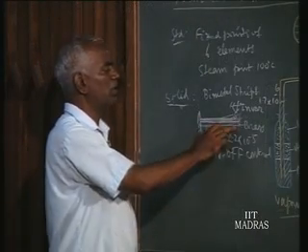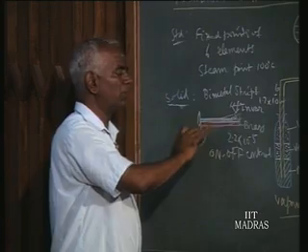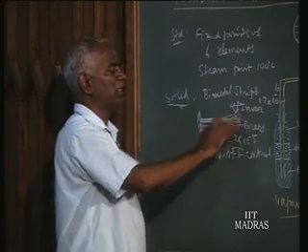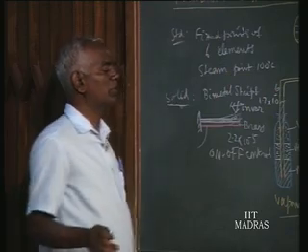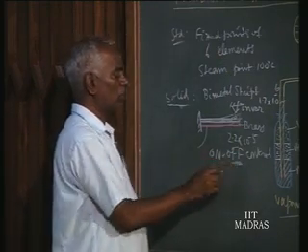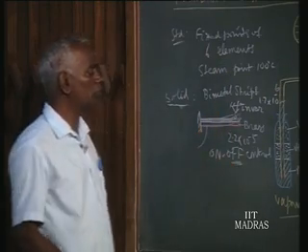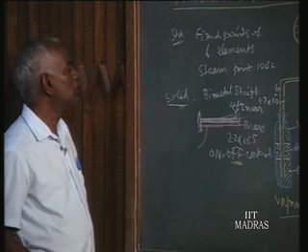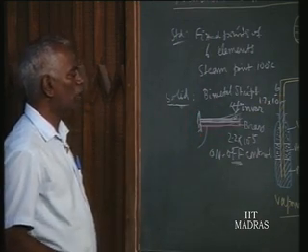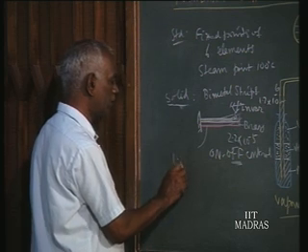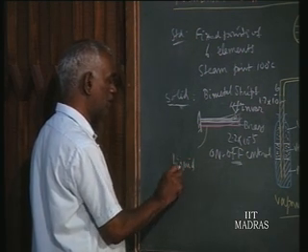Here it is measured, and measurement is done by bending. When it is measuring, it bends this way or the other way, and that is being made use of for control purposes. It is called either on or off. It will be in two positions, two position control. That is expansion of solids. And now expansion of liquid, we are using in the mercury in glass